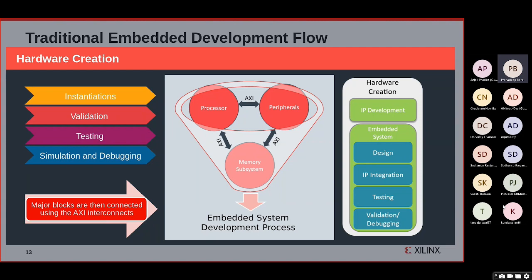And since we are living inside an ARM processing environment, in your phones, if you see inside your Qualcomm chip, there is an ARM processor. In your cars, in your washing machines, any kind of smart device, there is some configuration of ARM processor. So when Xilinx has been migrating from ISE to Vivado, all those peripheral IPs that we'll be creating, if we need to connect them to the processor, all those peripherals and the memory subsystem should have an AXI interface.